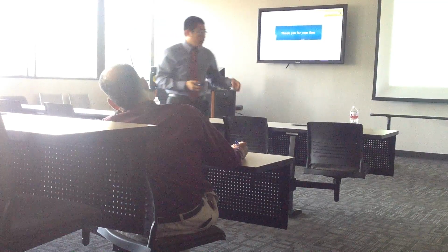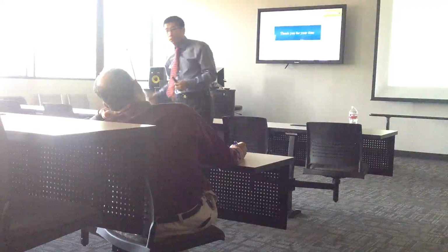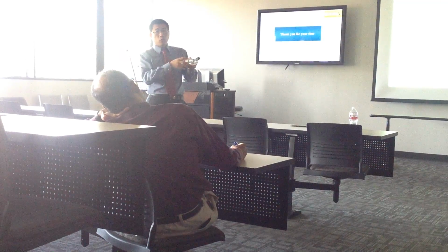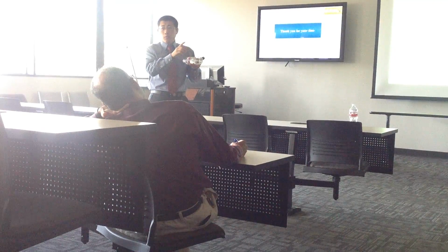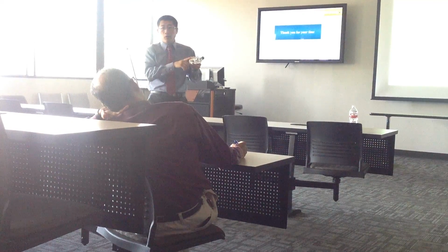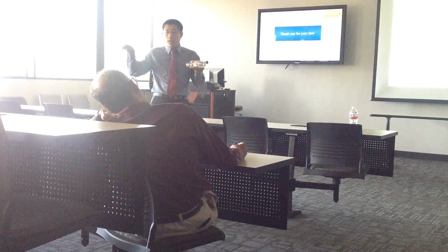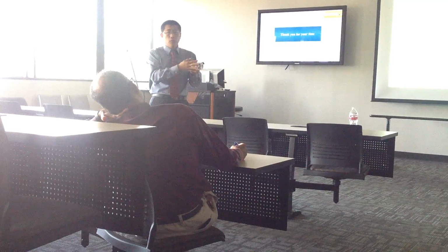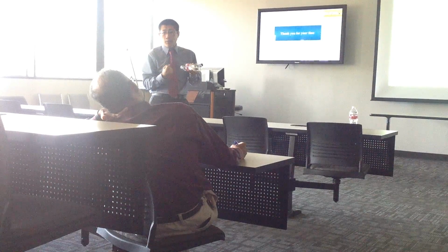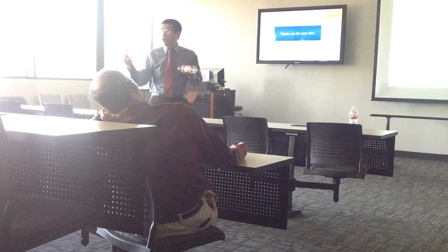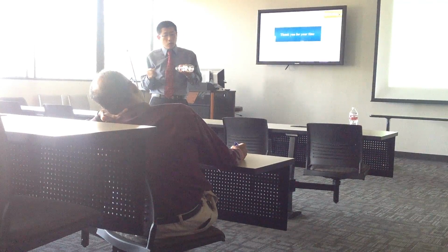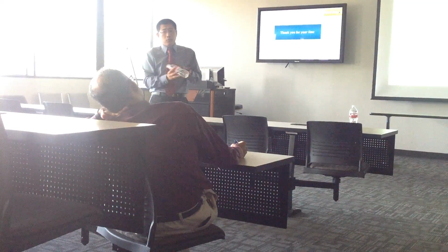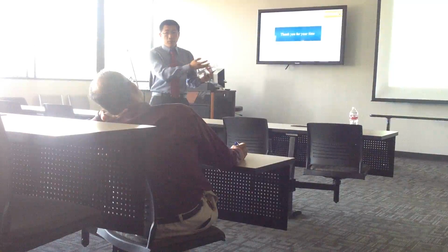If you just want to study, for example, this bottle, it's so simple, just a cylinder, you don't need to use this very complicated model. Another model, for example, the K omega model or K epsilon model, can also simulate the flow situation, and the result is also acceptable. And it's much easier for people to operate, and sometimes the calculation time can be reduced. So that depends on the different study case.